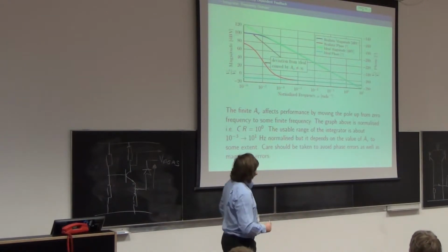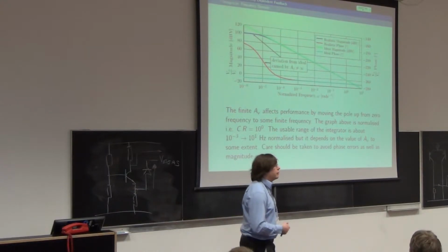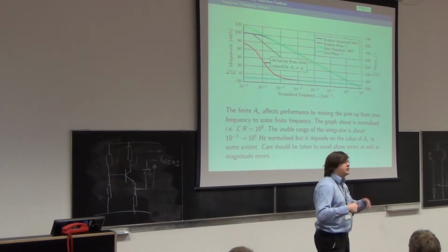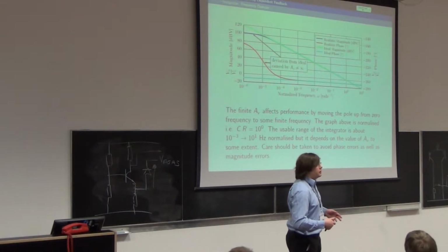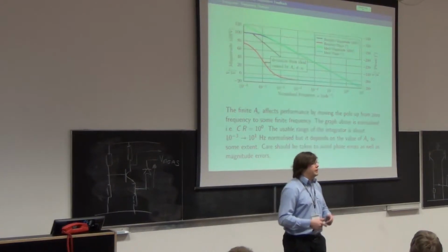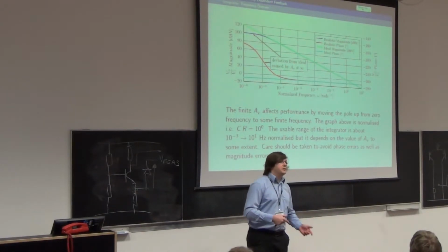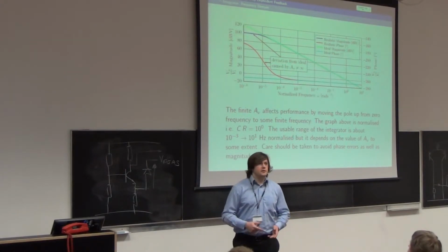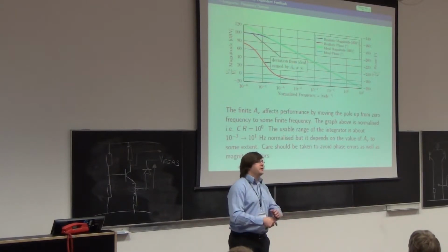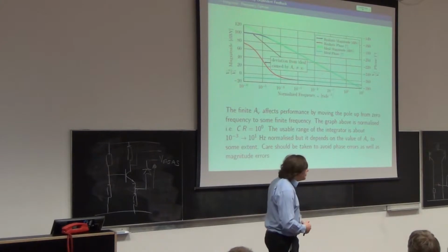even when it's not. Oftentimes you do that in Spice because a lot of the time you're not worried about some particulars of an op-amp that requires you to simulate 30-40 transistors. You just want to know what your circuit's going to get up to if the op-amp's ideal, and you'll make the assumption the op-amp is ideal. The reason you want to do that in your simulator is simulating a really, really big circuit takes quite a long time, even in quite a tasty computer. Let's assume you don't have loads and loads of GPUs sat around to do some parallel processing stuff.